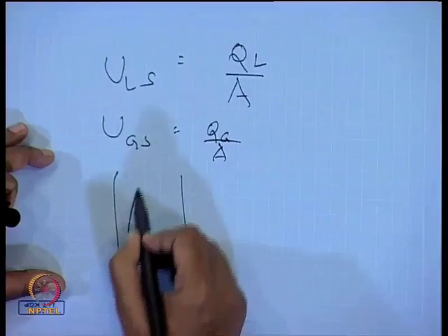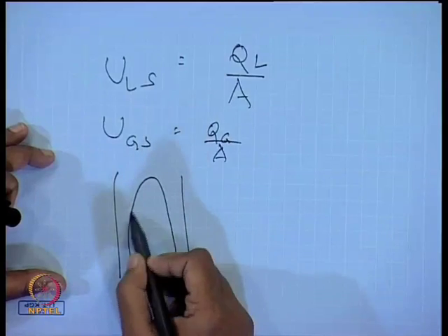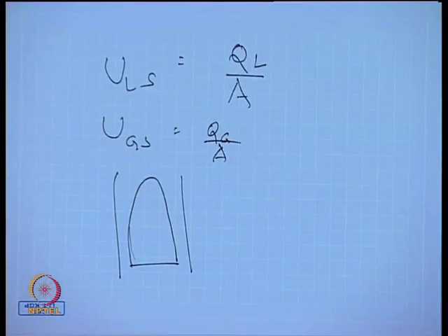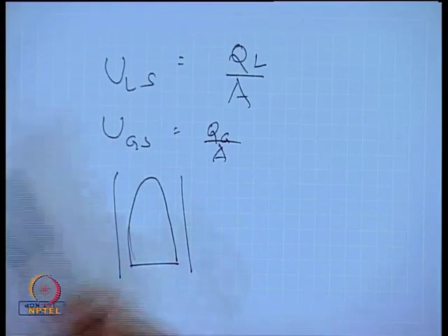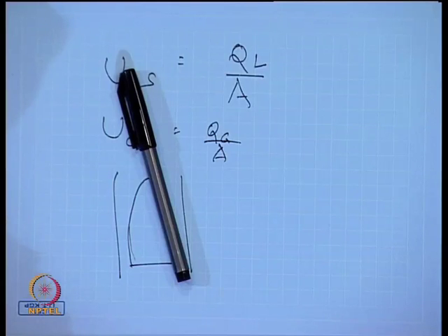So, this was what we found out, and I have already described the Taylor bubble to you. It comprises a bullet shape with a hemispherical nose and a cylindrical tail. Now, this shows the Taylor bubble in a circular pipe as well as in a rectangular channel. In a circular pipe, the Taylor bubble has a circular cross section.